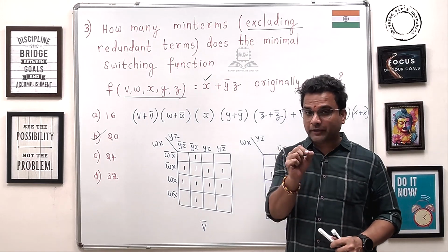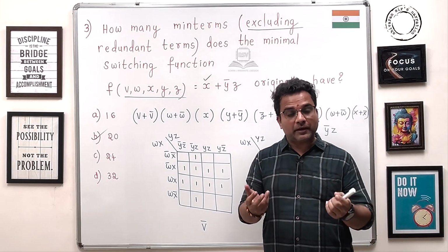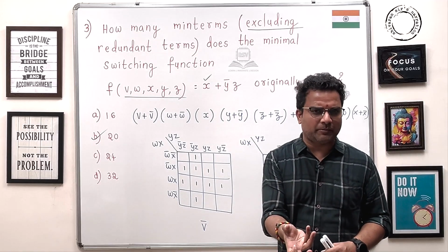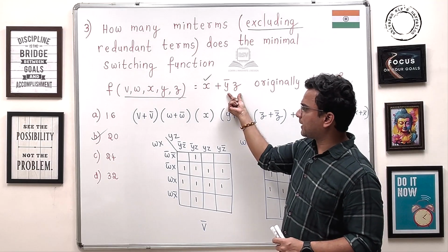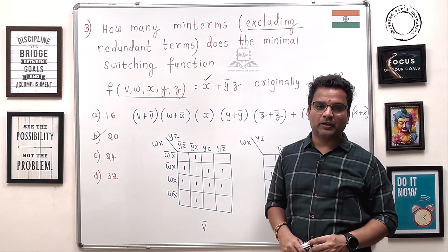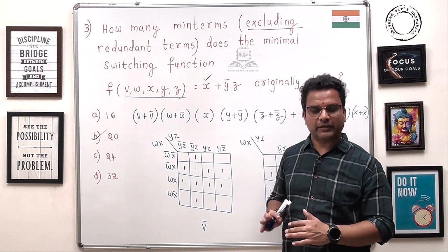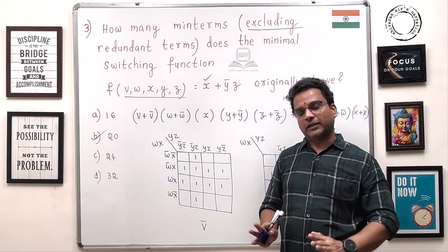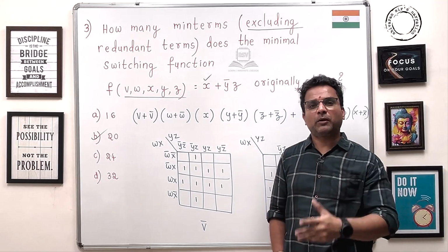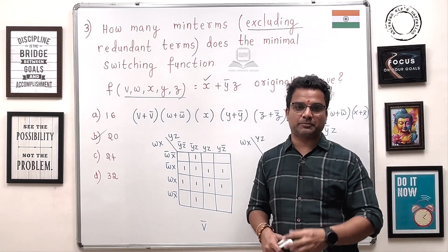And here is one important point that we must know, and people might be in ambiguity. This is only the simplified expression, right? Here you require fewer hardware elements. Obviously one NOT gate, one AND gate, one OR gate, that's enough. If you convert again into standard SOP, then you require more hardware elements, isn't it? Then why are you converting? Yes, I agree. As per the procedures, we need to know how to convert a minimal function into a standard SOP. Agree. But where do you need it? In standard SOP, you require more hardware elements, right? You can ask me.